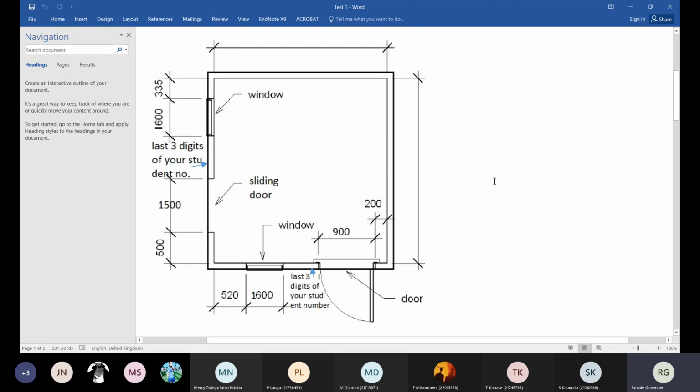All you had to do was, they told you that the ceiling height was 2.5 meters and you had a gable of 1.2. Obviously, the gable would have gone on the upper and the lower walls, because that's the shorter dimension. And you'll notice that it's fairly straightforward here again. So it would have been 2 times the length plus 2 times the breadth, times your 2.5 meters, to give us the area of the wall along the ceiling height. Then you would have had to add the gable.